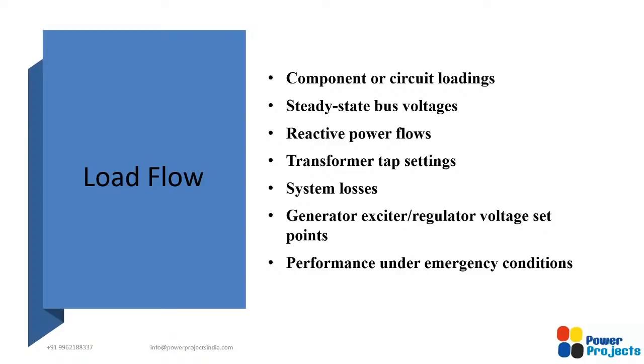Right. One most important point IEEE 399 misses, because IEEE 399 is not really covering that, is steady state stability. Because IEEE 399 is talking about power system analysis for industrial and commercial power systems, right? So in industrial or commercial power systems, the angle separation is not far, all the equipment is within a small place, so the angle difference between sending and receiving end voltage is not much. So that's the real reason why they have not really covered it.